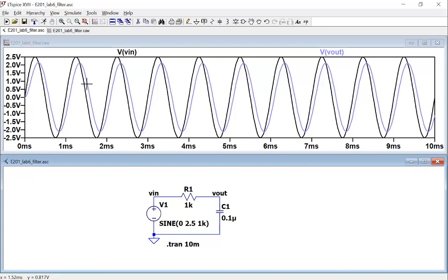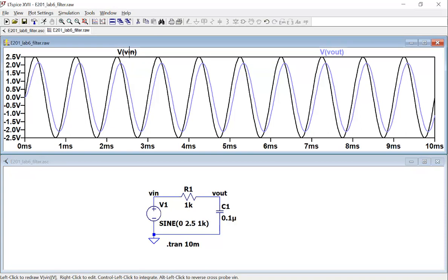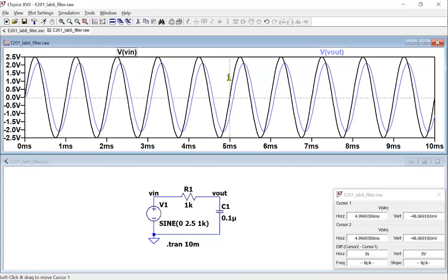So what's the next step? Assuming this is your oscilloscope, activate two cursors, measure one, and measure the other one. Because that signal is given, the input comes from the function generator, so you don't have to measure it. You know what's going on. It's going to be 5 volts VPP, okay? Then you just want to measure your output.